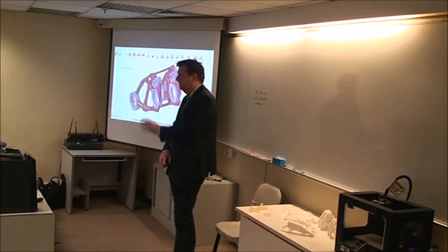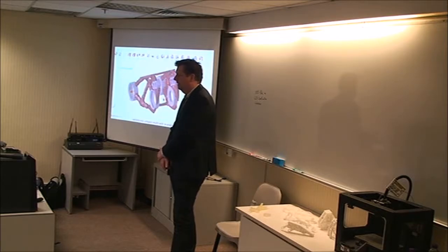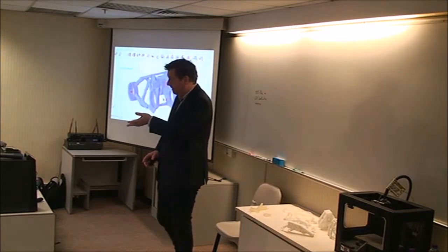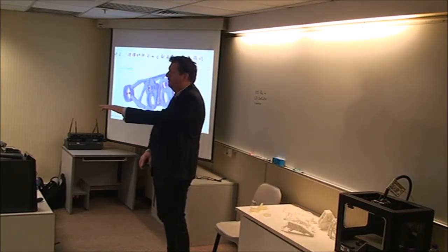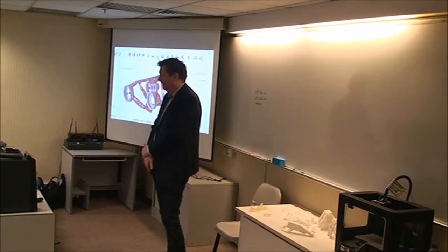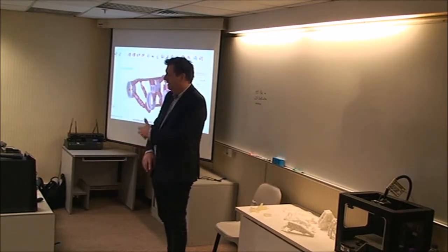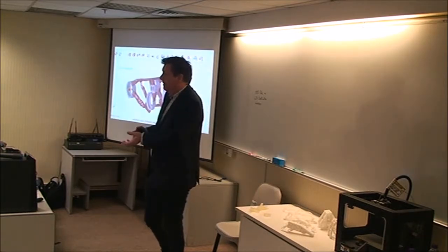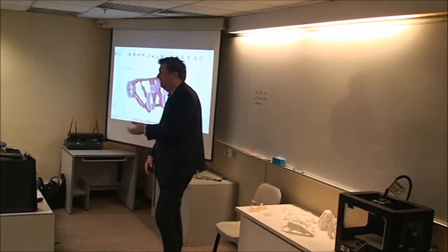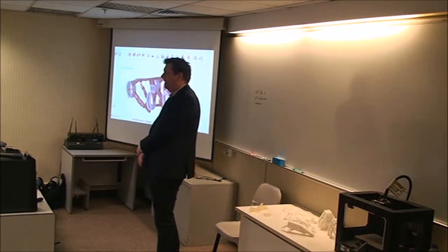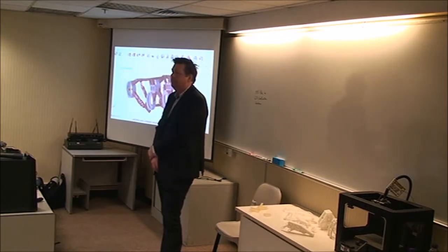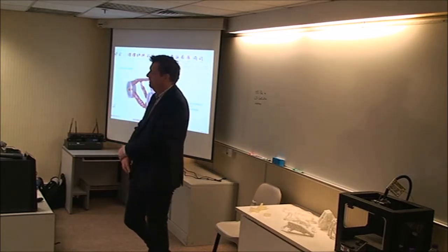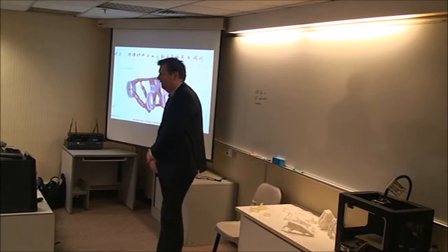You change the threshold, hit this little analysis button, and you'll get an answer. And change the threshold, run it again. And that was actually real time, I think. So that's how quickly it runs. If you do it on these computers, they might be a bit slow. So again, different concepts, maybe using different manufacturing methods. No constraints, draw direction, symmetry, no symmetry. So you just really quickly run through and check all your concepts and find out which ones work for you. So use it as a thinking tool. It's not the answer. It's a really cool way to get to something interesting.